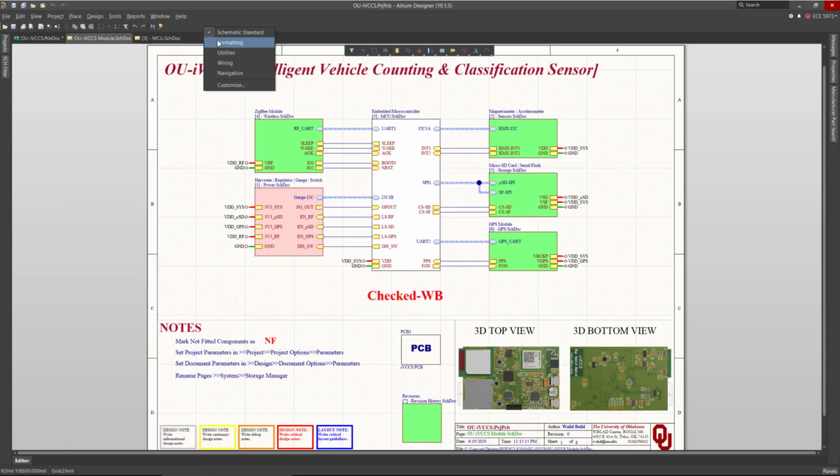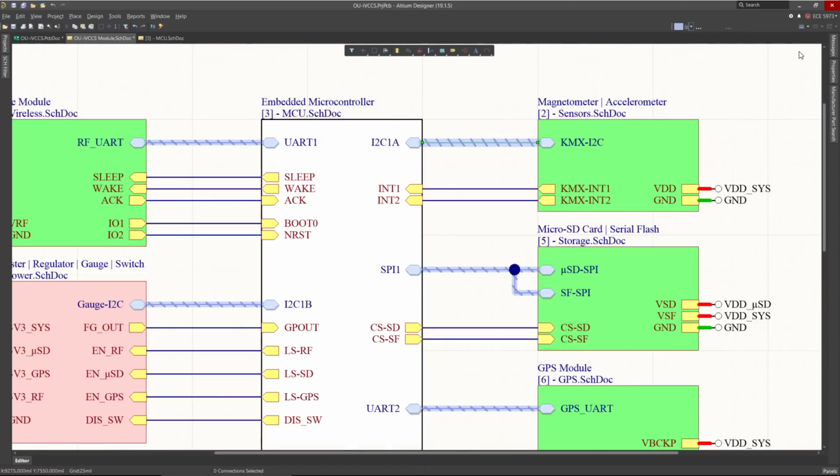Also, if you right-click formatting, for instance, when you click on the object associated with some of the commands in this menu, you will see it. So the thickness of this wire, you can change it in here, and this is active. If you click in the free space, it's no longer active, it's grayed out. Because it's also contextual, you can change the color, for instance. If you click in the free space, you cannot change the color from here.